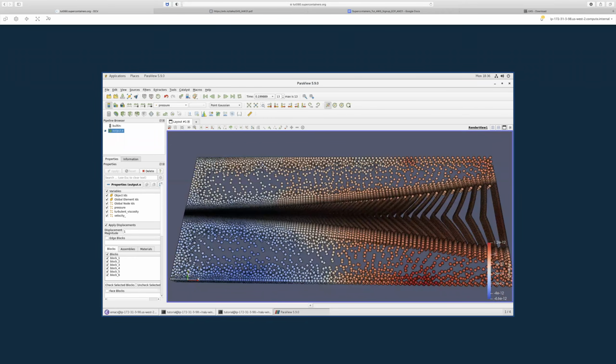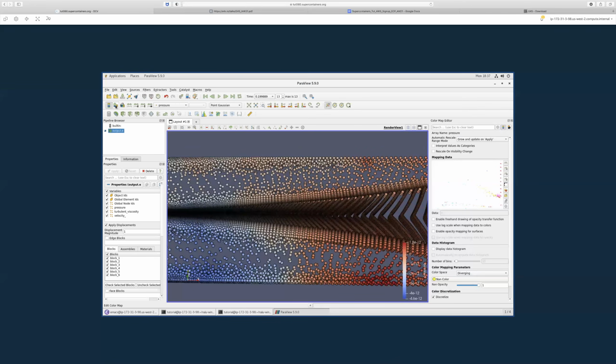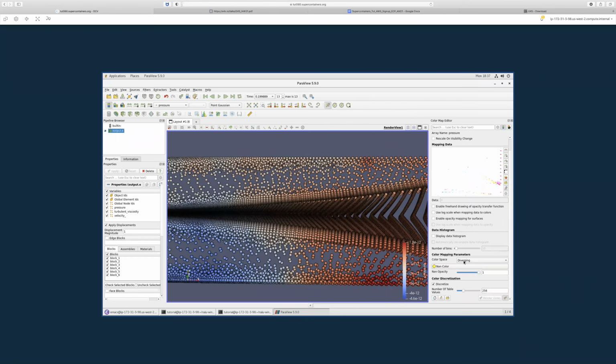Yes, I was able to visualize the output in ParaView, and if you want to adjust the color map scaling, the two buttons left of that pressure drop-down menu will adjust the color map to the range of the animation. Okay, these two, the color map setting. Well, a couple more buttons in, but at any rate, I think it doesn't really matter. We are able to see.